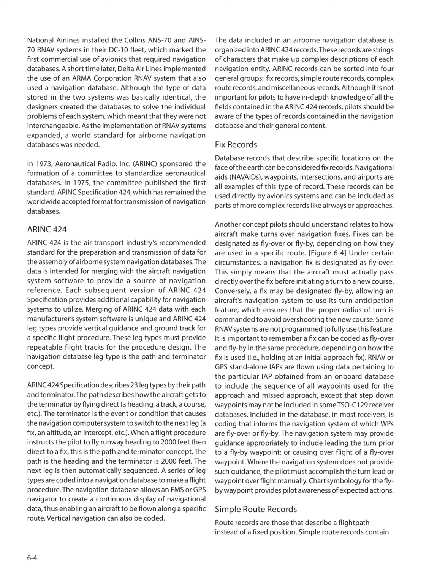RNAV or GPS standalone IAPs are flown using data pertaining to the particular IAP obtained from an onboard database to include the sequence of all waypoints used for the approach and missed approach, except that step-down waypoints may not be included in some TSO C129 receiver databases.